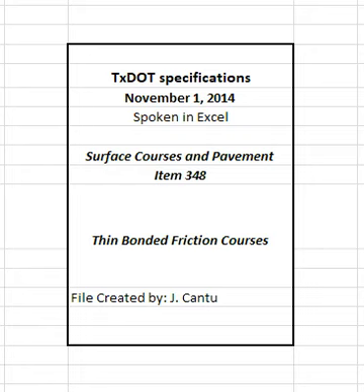Procedures for the transfer of mixture into the paver while avoiding segregation and preventing material spillage. Process to balance production, delivery, paving, and compaction to achieve continuous placement operations and good ride quality. Paver operations, for example operation of wings, height of mixture in auger chamber, to avoid physical and thermal segregation and other surface irregularities, and procedures to construct quality longitudinal and transverse joints.